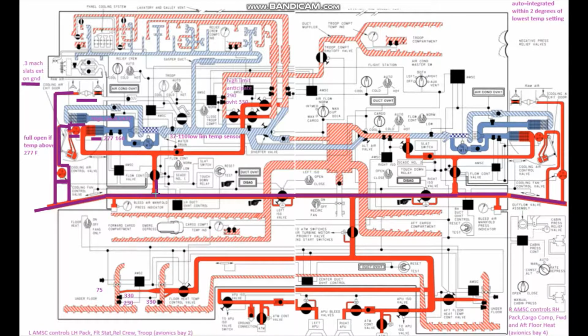Alright, back to the flow control valve. So the flow control valve, if you have it in normal, we have bleed air coming from the cross-ship manifold, it will open up, and we've got kind of a Y where bleed air can go. So we'll just follow it this way since it's going to be standing by over here. So it'll overcome that check valve, come up here, and we'll end up with hot bleed air in this area here. So these valves, they're drawn open right now, but bleed air will stand by there to kind of do some work later, and I'll explain that.